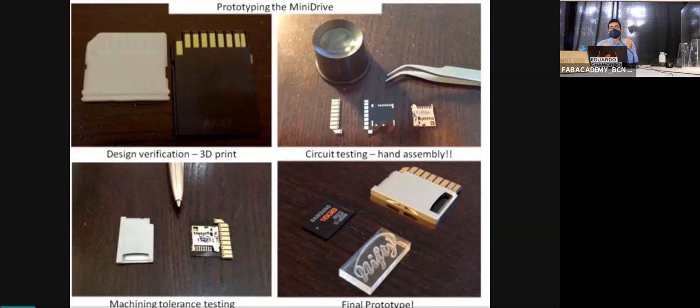For example, something that I will say is mandatory for this week, and for the challenge, is you never cut your design directly on the CNC. You scale it down 1 to 5 or 1 to 10, and you cut it in the laser cutter.